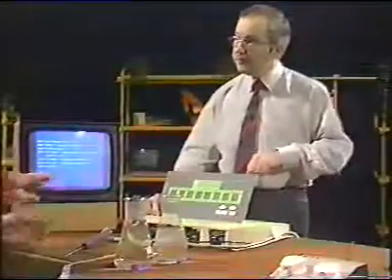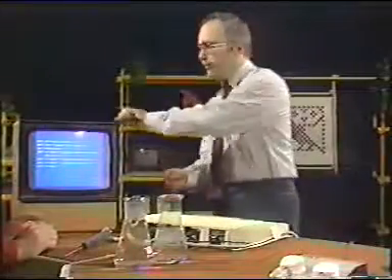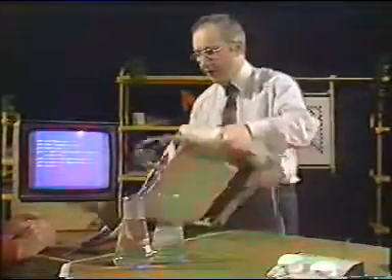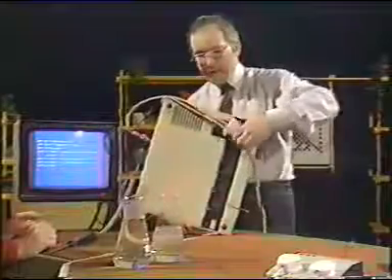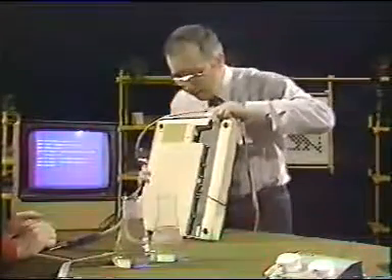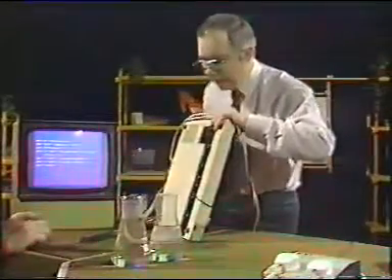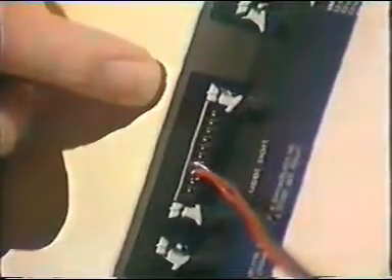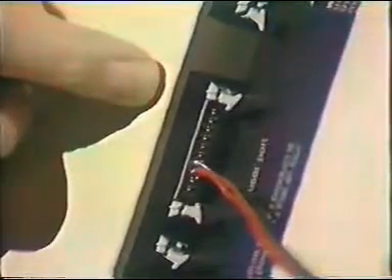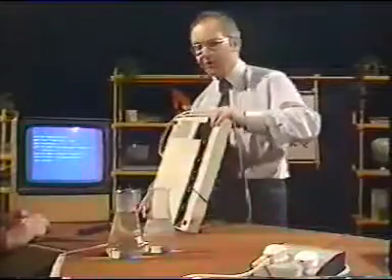Well, how does the actual output work? Well, we use the same port that we used last time for driving the lights, but this time we instead drive the fans. You can see there are 3 leads coming off there. One is an earth connection, and the other 2 contain the signal connections to say that the fan or the heater should be switched on. And there are in fact 6 other unused connections corresponding to the 6 bits in the byte that we weren't using. Let's follow down that wire and have a look at the control box.